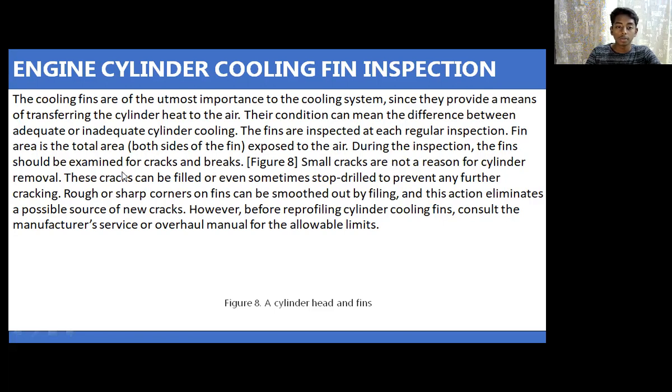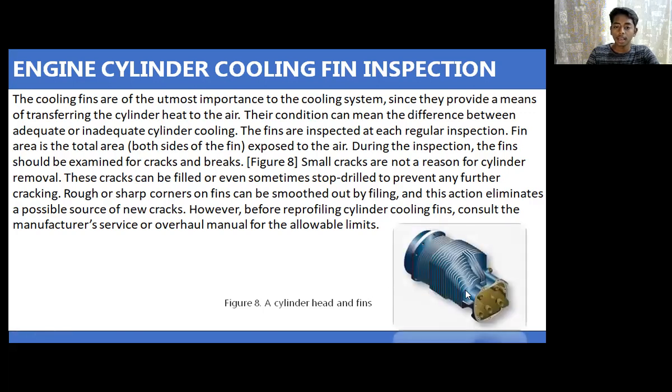The fins should be examined for cracks and breaks. At higher speeds, if fins have any cracks or breaks, they are going to separate from the main part, and the whole aircraft could be destroyed. As we can see in figure 8, small cracks are not a reason for cylinder removal. These cracks can be filled or even sometimes stop drilled to prevent any further cracking.